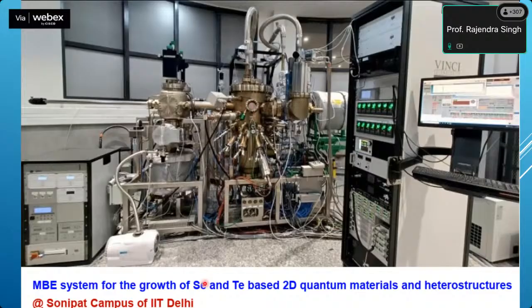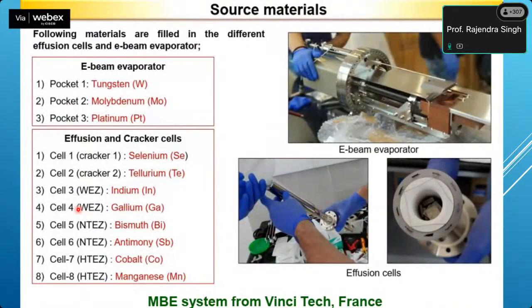It is one of the first MBE systems in India on selenium and tellurium based 2D quantum materials. And what are the various sources we have available? As I was showing you in the first graph, energy band gap versus the lattice constant, what are the various materials you can deposit, and how can you engineer the growth and tune the band gap? We have tungsten, molybdenum, and platinum, and in the K cells we have selenium, tellurium, indium, gallium, bismuth, antimony, cobalt, and manganese.